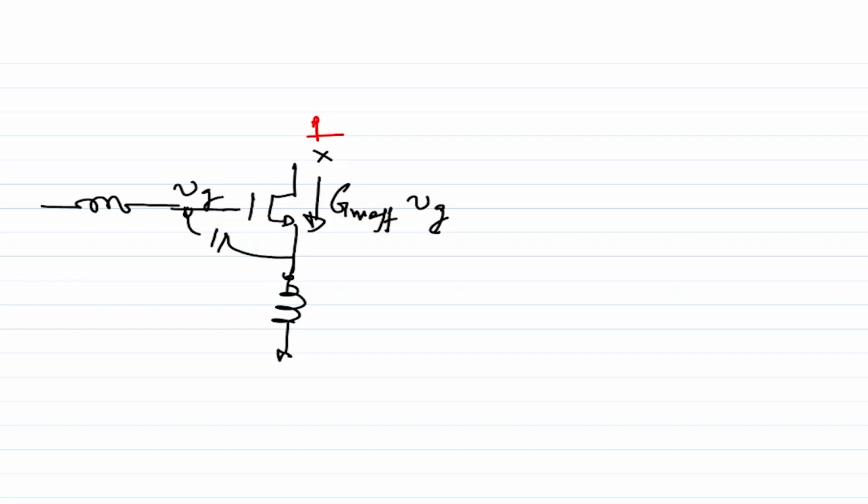So just like one of our examples before, where we did the common gate configuration, we can put in a cascode where incrementally this is shorted, and then you take the output. If we want to see the entire biasing circuit, this is similar to one of the cascode biasing networks that we had done earlier.